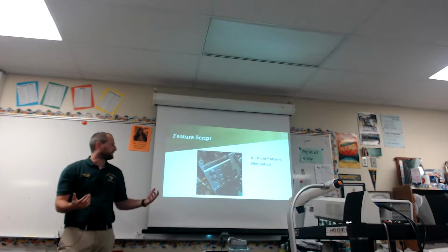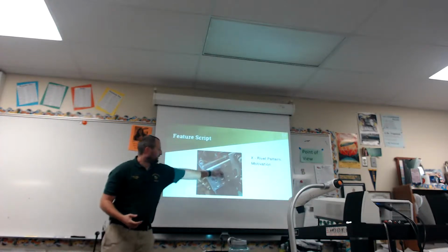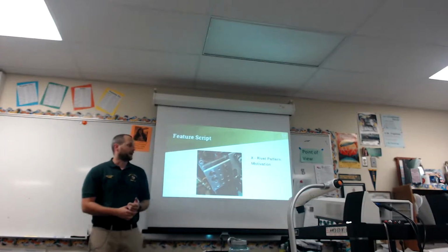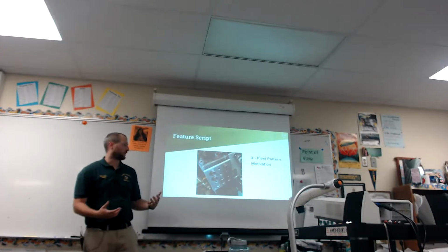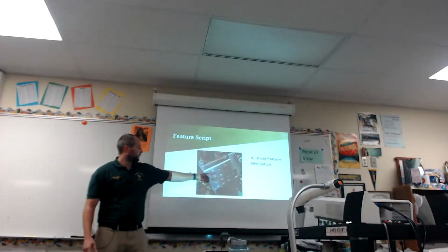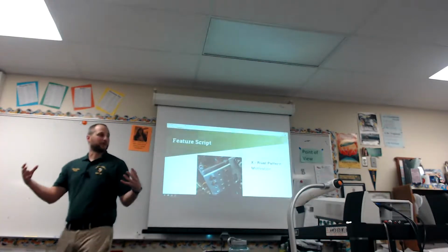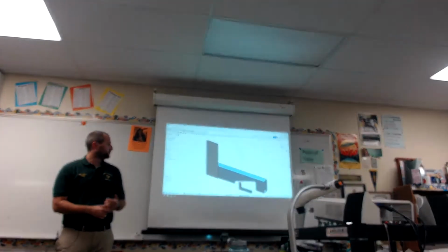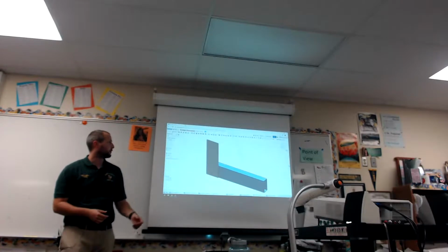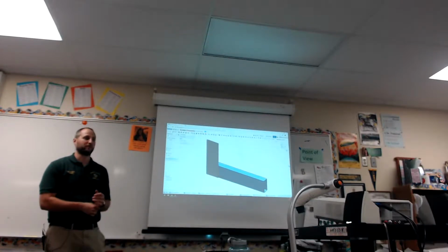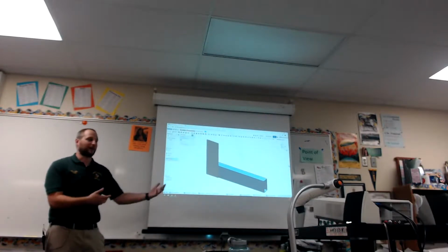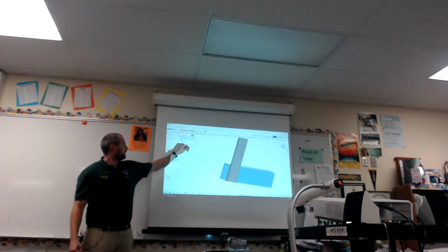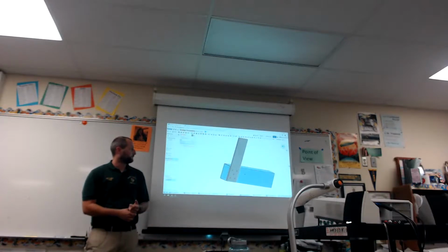So the motivation behind this is we don't need 12 holes here, we could get by with 5 or less. So I built a custom feature script to show the design team how well this works, where it just makes an X pattern with some spacing based on standards that we've come up with within our team. And so Tony's going to show how quick and easy it is to actually call on a feature script that you've made. So anybody on my team can access this. It tells him what his inputs are needed, right? What parts you're going to cut.